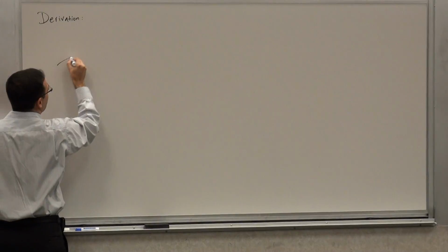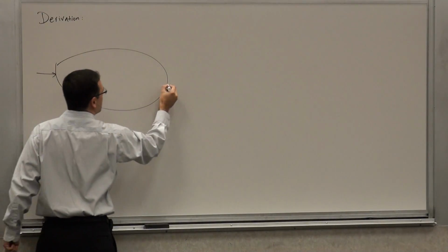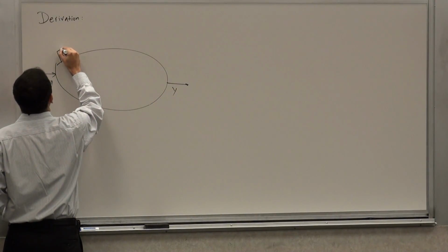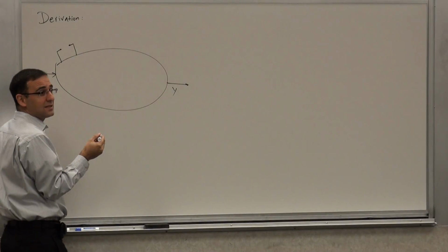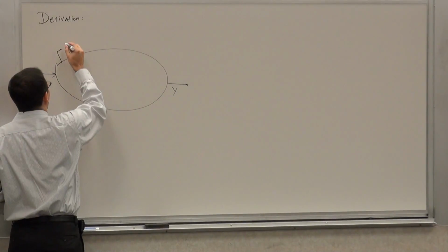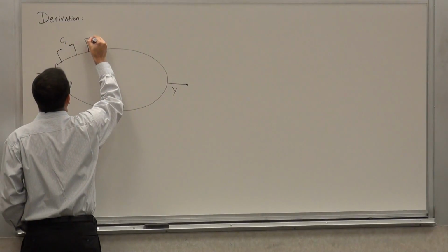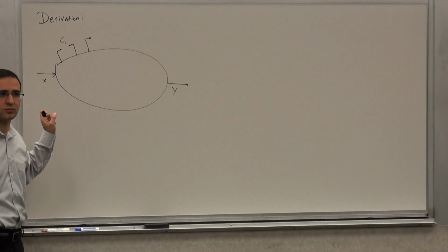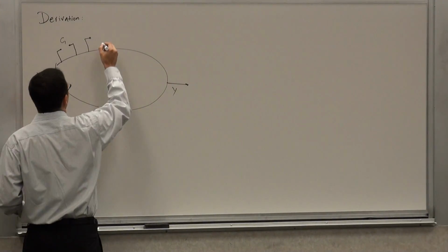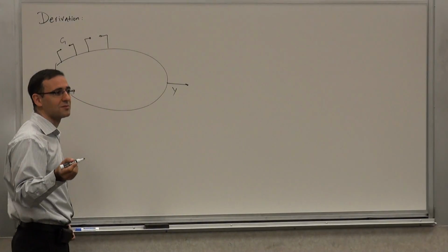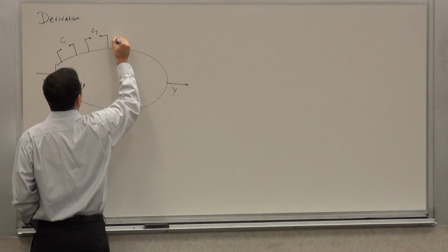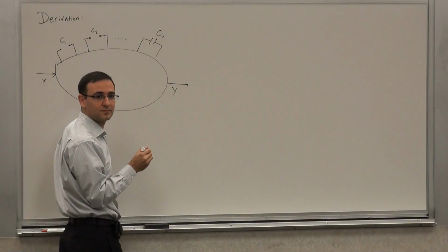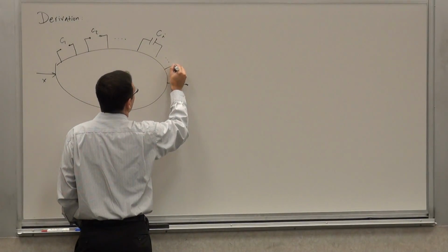is that, okay, well, let's take the same system with n energy storing elements, x and y, and n ports. And let's just zero value all the elements. Let's take that system and say, well, I'll zero value all the elements. And now in the beginning, let's assume that they're all capacitors. And I'll tell you how it would look when you have inductors as well. But let's just do it for capacitors because then I have to write one sum as opposed to 2 sums. But it's exactly the same derivation. So except you keep the Ci, the ith capacitor. And all the other ones are zero value.